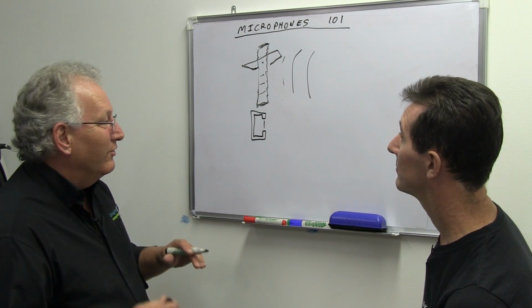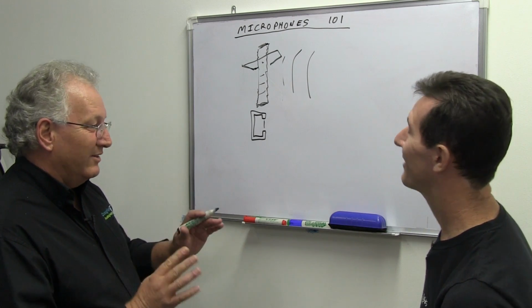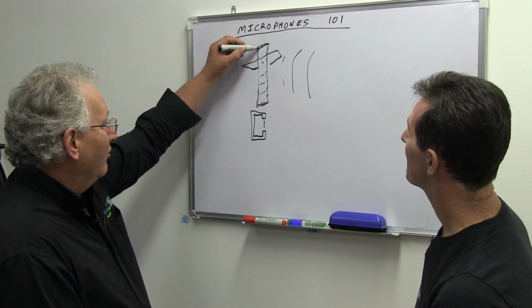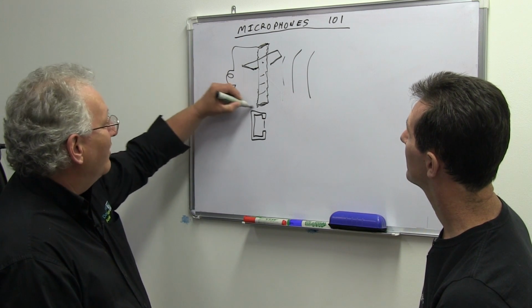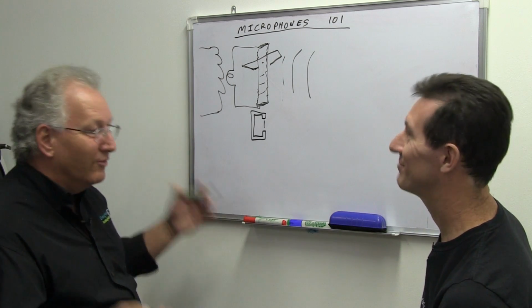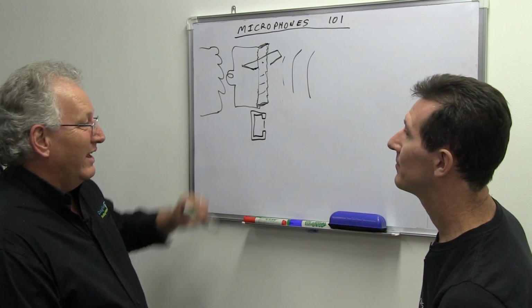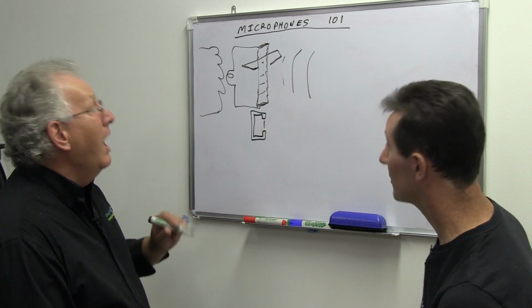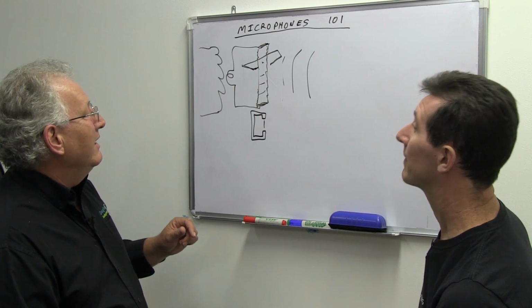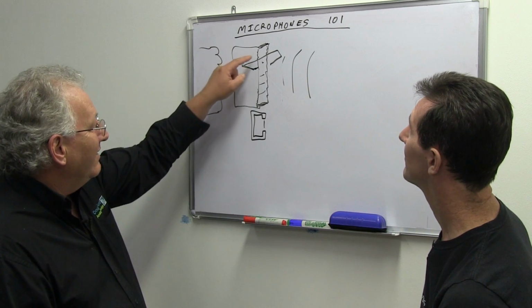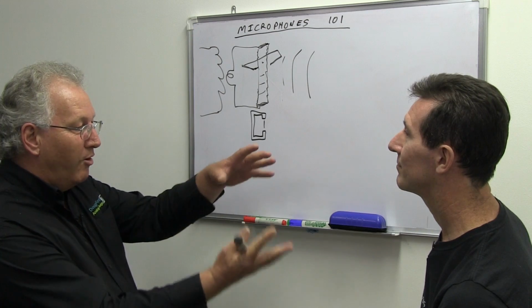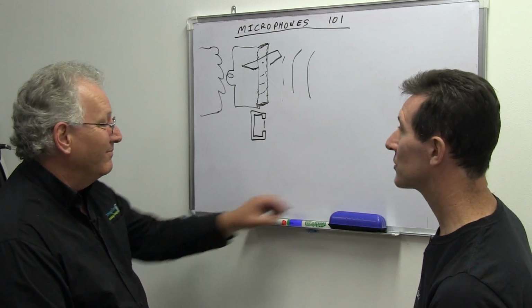They're considered by a lot of the studio fraternity to be the duck's guts. But there's an issue. The voltage coming out of those is so low that you often have to put those into a transformer, with a couple of turns there and a couple of quadrillion turns over here, to get any useful voltage out of them. The impedance of that is way under an ohm. They're also reputed to be relatively fragile. If you go at them, that corrugated sheet of very, very thin aluminium just goes thong. Boom. Game over.